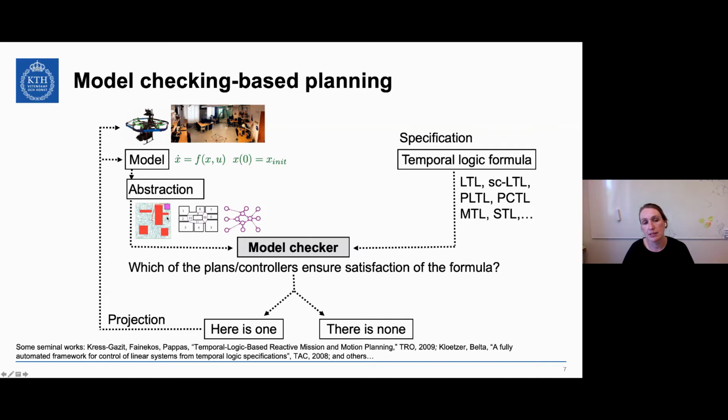One way to discretize this is through sampling-based motion planning algorithms. You build an RRT star, and then you treat this RRT star as a sort of under-approximation of your original system. Or you can build different kinds of abstractions based on partitioning of the environment, and then looking at the dynamics of the robot and saying that you connect region 1 with region 9 if you can actually control the robot to drive from region 1 to region 9. This is an important step that I will not be talking too much about today, but it needs to be remembered that the question of how you come from an autonomous robot to a system that can be handled by a model checker is a non-trivial question.